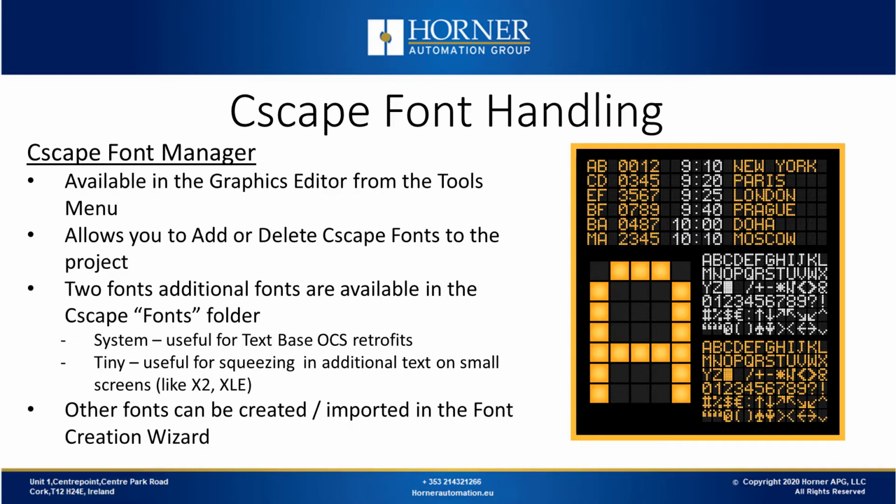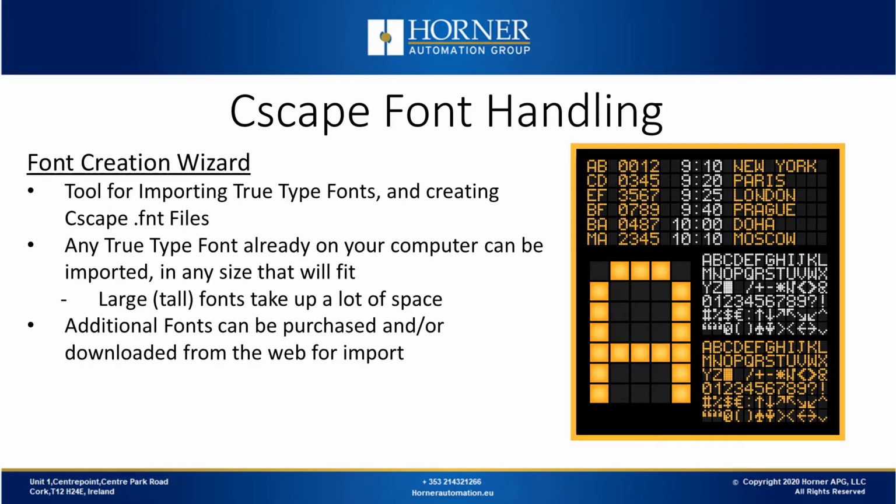If you look in the default installation of Cscape in the fonts folder, you will find a couple of fonts in the system. In addition to these .fnt files, other fonts can be created or imported using the Font Creation Wizard. The Font Creation Wizard is a tool for importing TrueType fonts and creating .fnt files. You can import any TrueType font that's on your computer, any size that will fit. Additional fonts can be purchased or downloaded from the web for import. Many free fonts are only free for personal use and are not free for business use unless you license them.